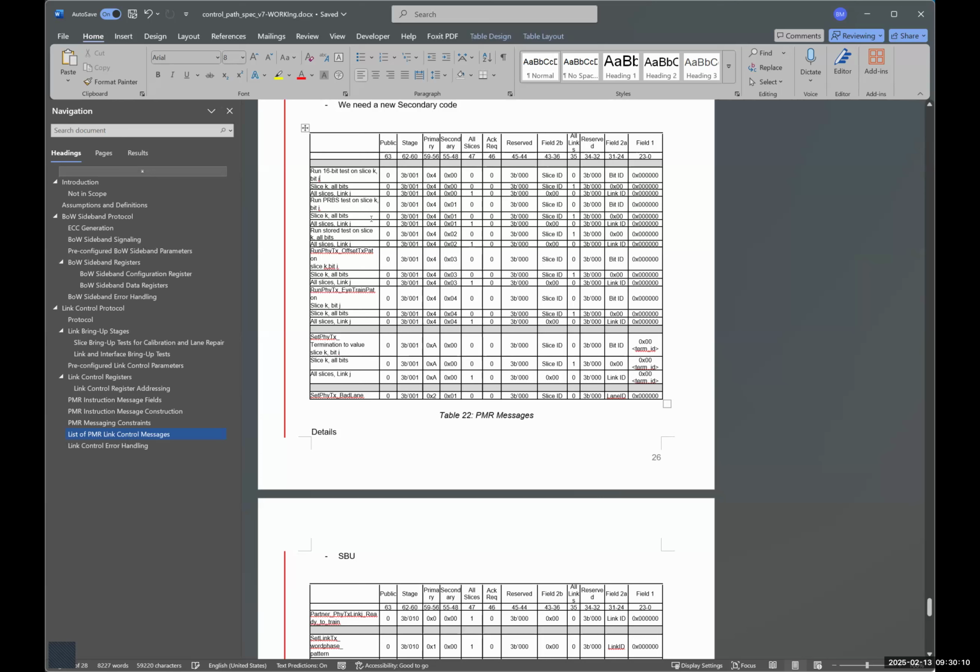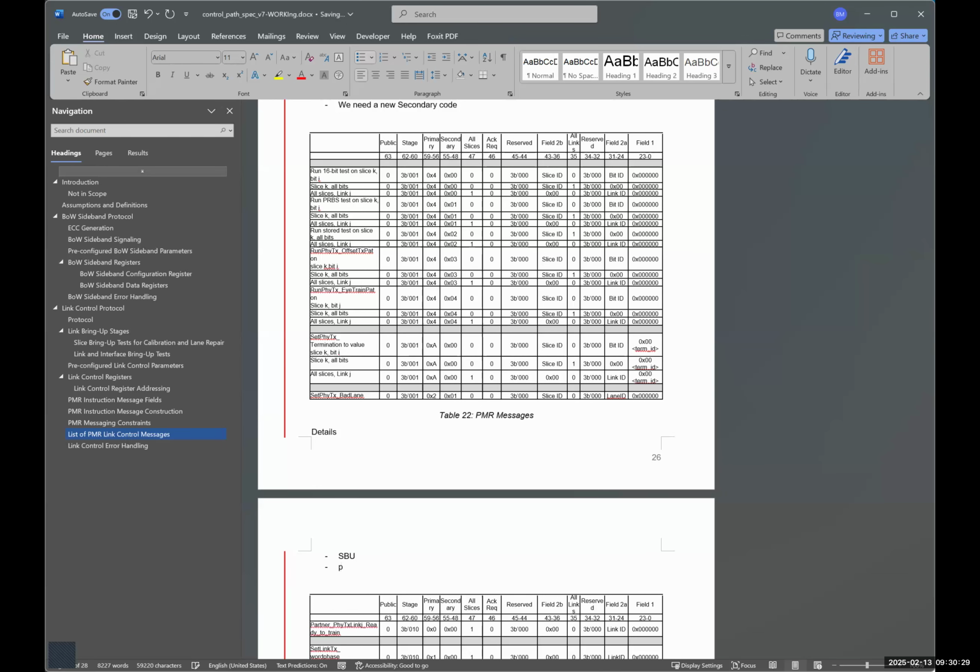Okay, so can you only do 16 bits if it is an explicitly defined pattern? Yeah, explicitly defined pattern, maybe yes. Okay, all right. I'll add text saying it's only the lower bits. But for PRBS, you need the whole seed. You cannot have just a part of the seed. Okay, lower 16 bits. I'll add some text on that. All right, moving on then.